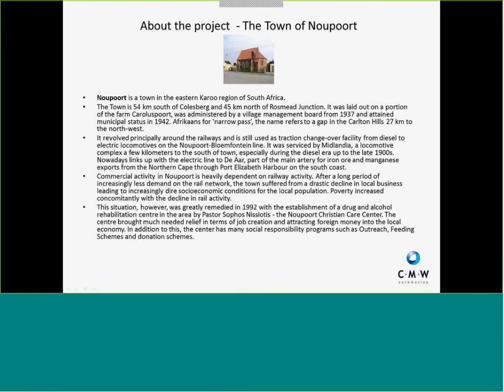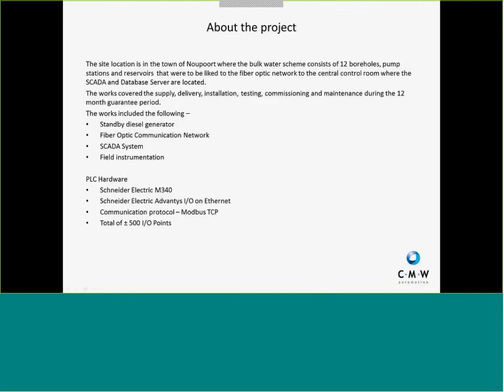And yes, we don't have any rivers or dams in the near vicinity, so the only thing is groundwater, or what we call borehole water. So this project was, and currently still is, based on 12 boreholes, 2 pump stations, and various reservoirs, all interlinked via a fiber optic network to a central control room where the SCADA and database servers are located.